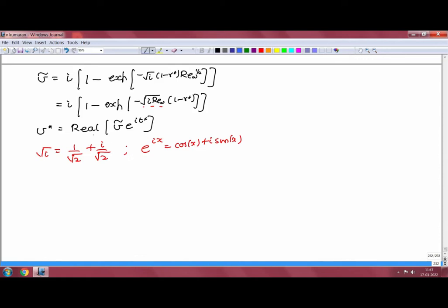So, this completes our analysis of oscillatory flows. I considered for you two cases. The original equation, in this case we could solve it and get a numerical solution. In many cases you may not be able to get a closed form solution. However, you can take limiting cases, Re omega small and Re omega large, and use a regular perturbation expansion in one limit to get the solutions for small values of the Reynolds number.